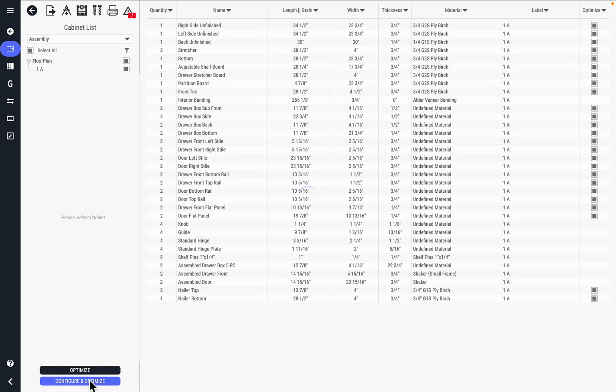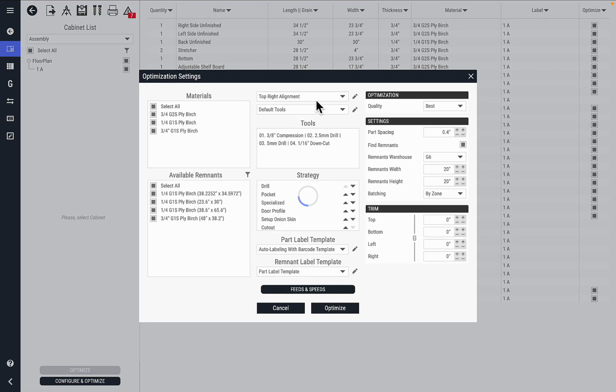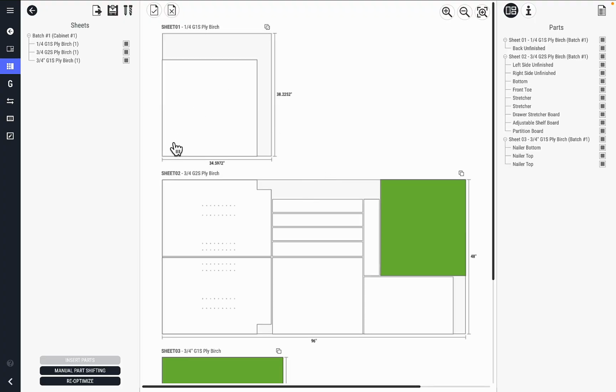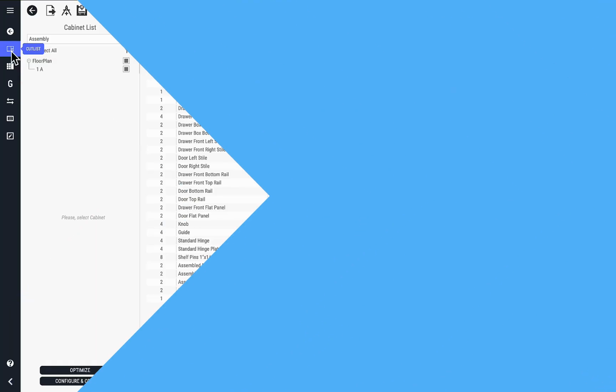And if I were to go back and use, for instance, the bottom left CNC alignment, we would push them instead to the bottom left corner. And so if you have some special needs where moving to positive Y would actually end up causing you some problems in manufacturing, you can now use this nesting orientation parameter to shift it to the appropriate corner.